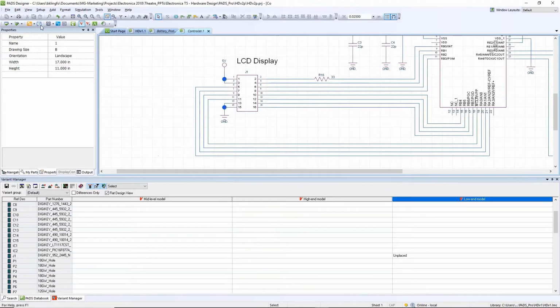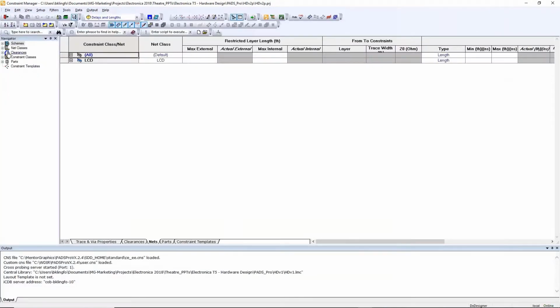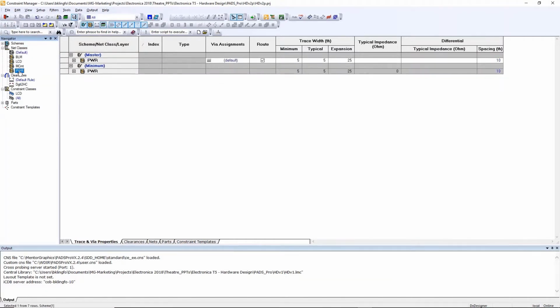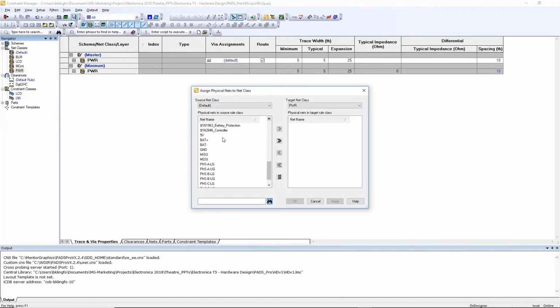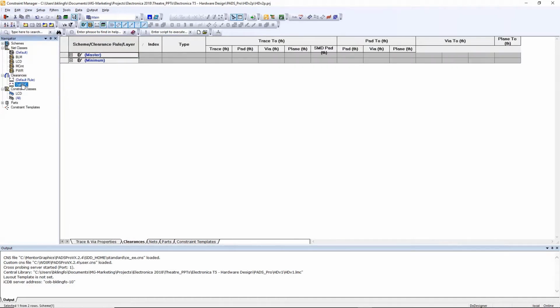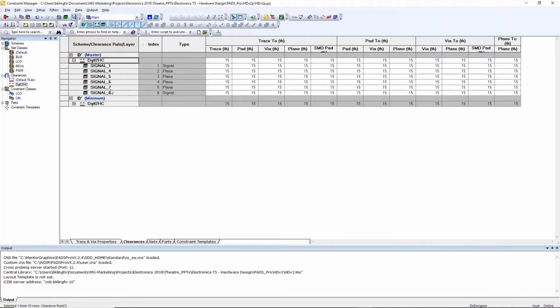Moving on, design rules are mandatory for doing a PCB layout. In many cases, it's much easier if you can enter as many design rules at the schematic level when you're thinking about your electronic circuits, or you've done simulation. So from Designer, we can open up the Constraint Management system, which is the same rule entry system you would use in the PCB layout.